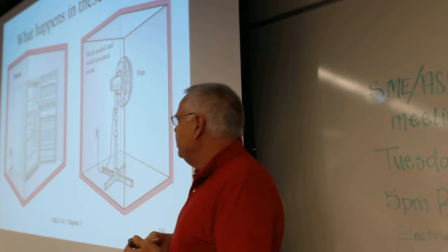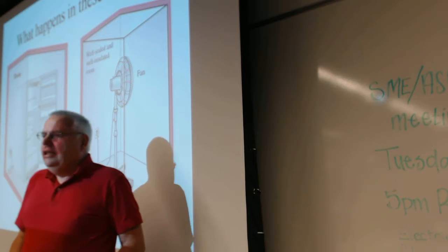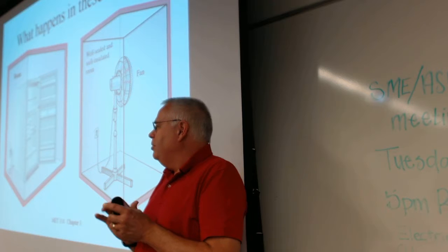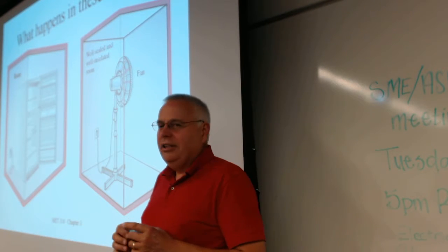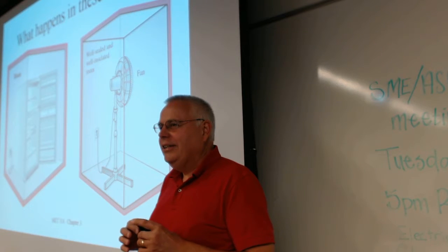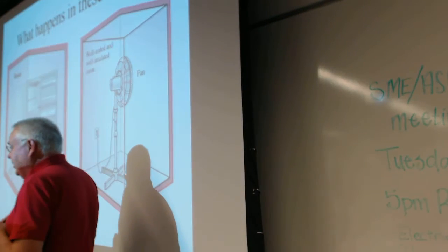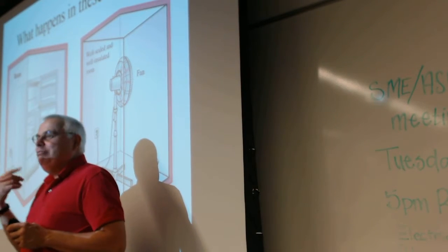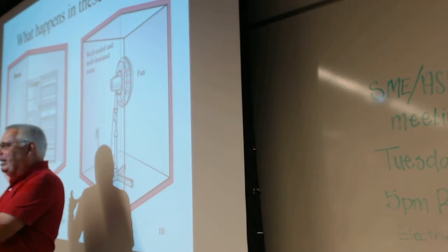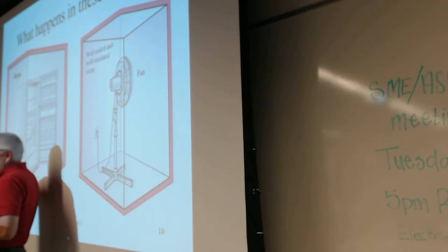So, imagine this. You got a nice insulated room. It's a really hot day, and you're thinking to yourself, my refrigerator is so nice and cool, I'll just open the door and cool down the room. Is that a good idea? Why is that not a good idea? Because your fridge is going to become the temperature of the room. Yeah, and will the room get any cooler? Probably barely a little bit. If it's mixed nicely, if you happen to be the guy that got the chair right next to the refrigerator, you'll probably be cooler. But what happened on the back of the refrigerator? Heat.